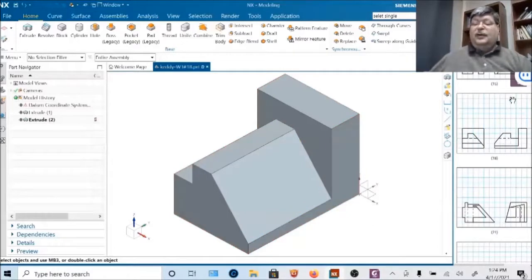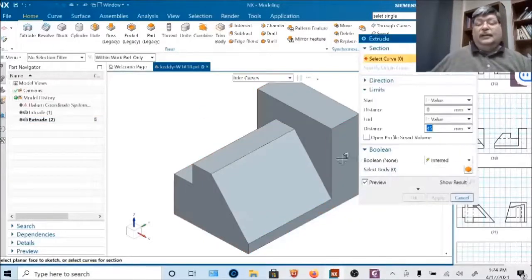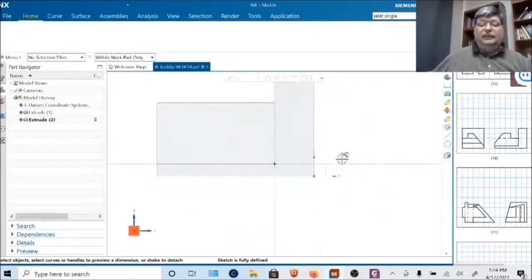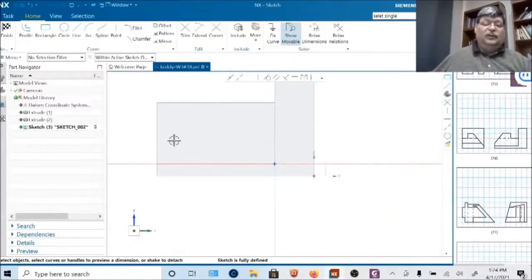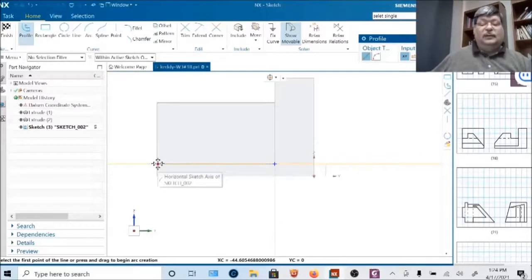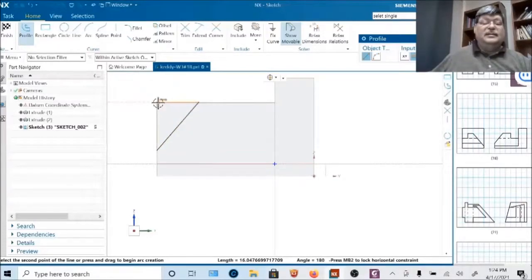Now, in order to create this inclined plane out front, we would have to go to the profile view, like here, and draw, and it would rotate it, right? And then we'd have to draw like a triangle here and subtract it through there. And we can do that. Might as well. It starts where at? It starts 10 units up from the bottom. Something like this.